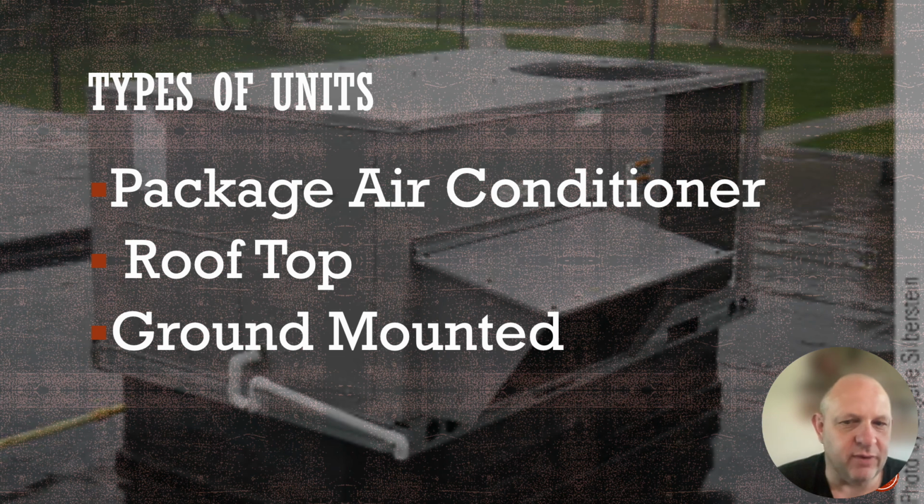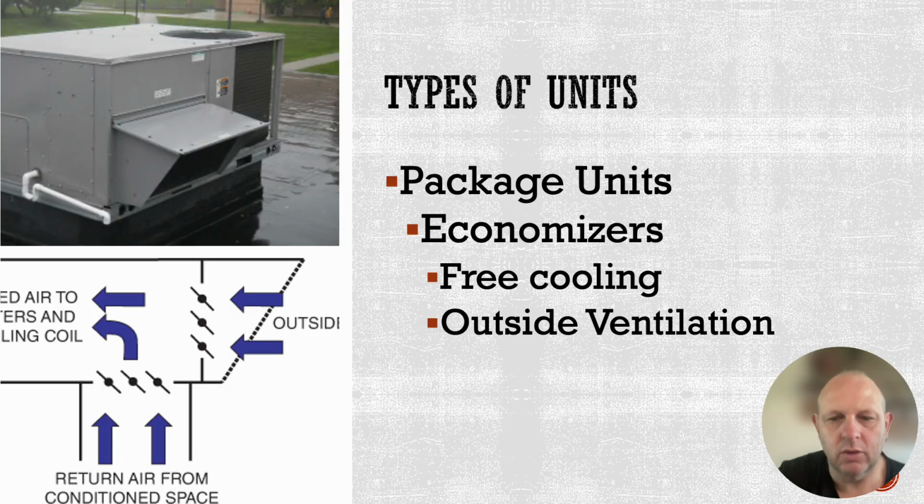Air is ducted in from the equipment into the facility, either through the roof curb or through ductwork that we are attaching to the unit itself. Package equipment may be located beside the structure, on top of the structure, but in some instances, the heating equipment is built into the cabinets as well. We can have electric heat, we can have gas heat, propane heat as well for these different types of units.